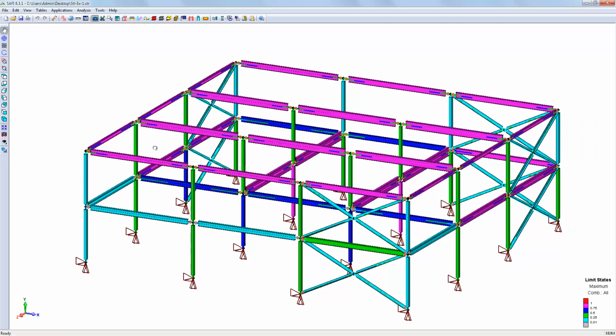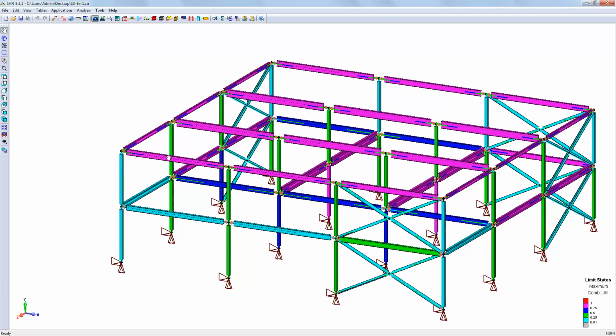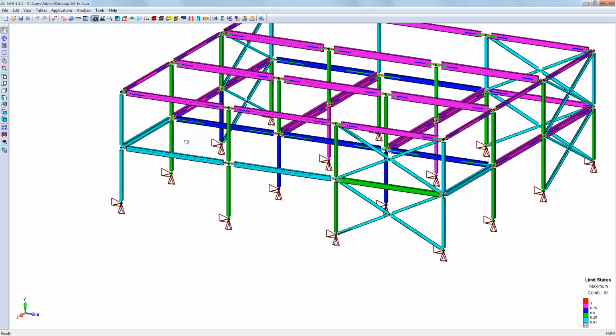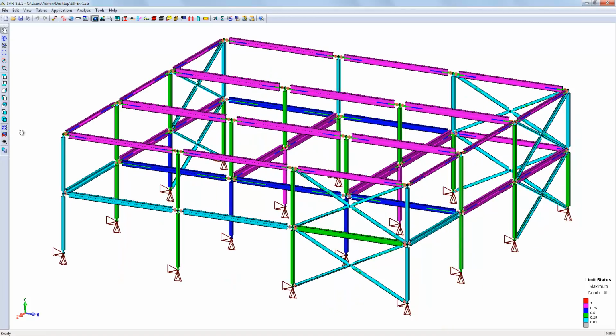By selecting the X direction, we can see that the structure only moves horizontally, and if we select the Y direction, the structure only moves vertically. The current option is marked with a check. To quit the command, press the Escape button on your keyboard.